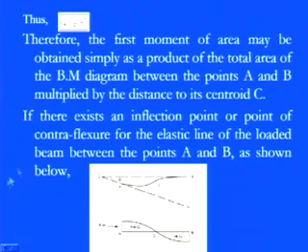We have a section O to B, and in between, if this kind of deflection curve is there, and we put the tangent on this particular part, and we have this kind of abrupt change in this. So for these, if you go for the bending moment, for this section we have a positive bending moment, and for this section we have a negative bending moment. So with that we have a point of contraflexure.